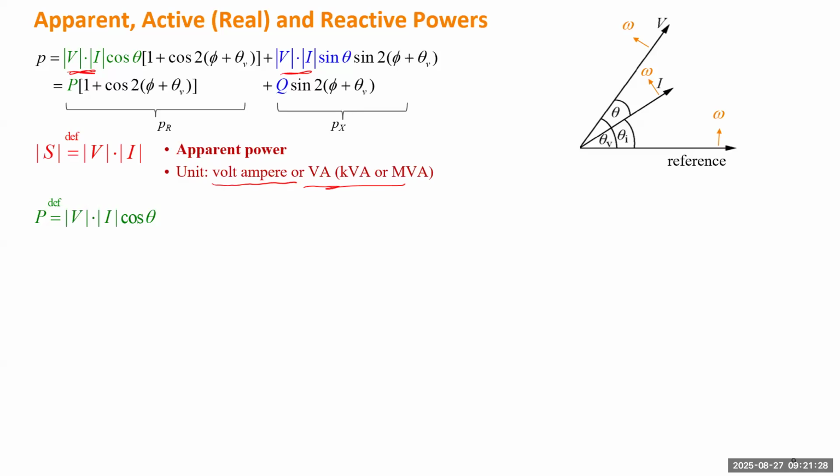Then this item is really the real power, because that indicates the power of the resistive part of the load. It is equal to the number 2000 in that example. And this one is really real power, or active power. You can call it either way; it's actually the average power. So we can use the unit W.